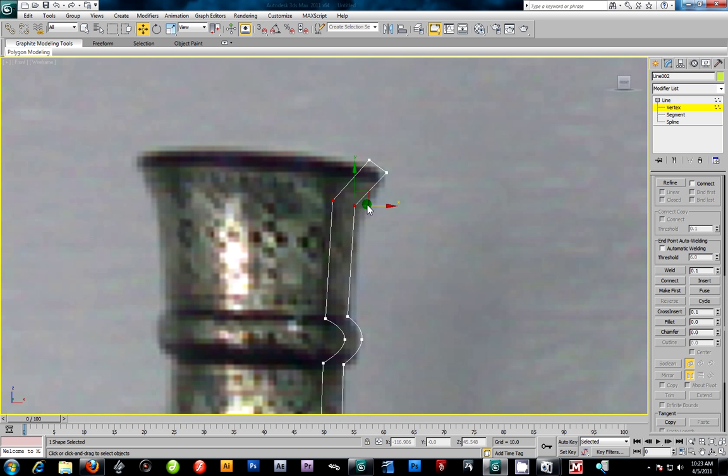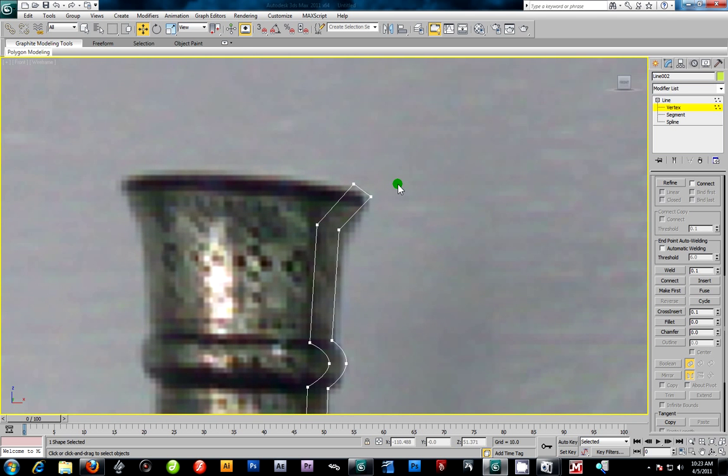So I'm actually going to, yeah, I guess we could smooth these, but before we do that, I want to show you the tops here. I basically don't want to highlight both of these and try to smooth them. You might get a decent look, but I'm going to teach you a new tool. I'm going to highlight both of these and come down here, and it's called fillet. With those two selected, I'm going to crank these up, and as you can see, it rounds off.